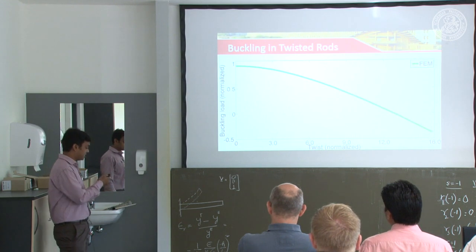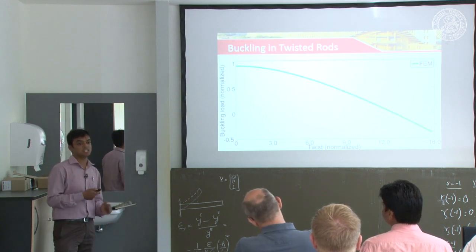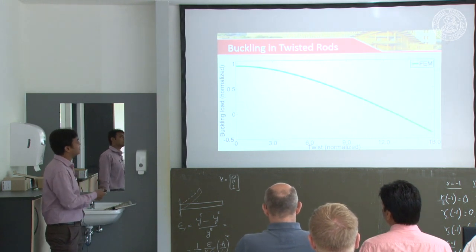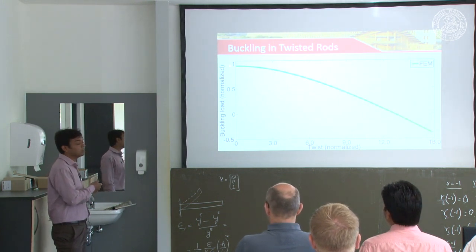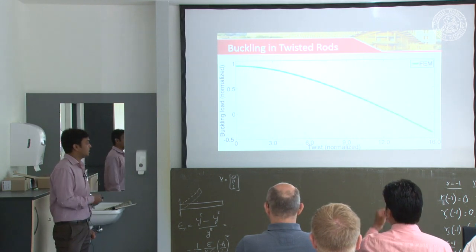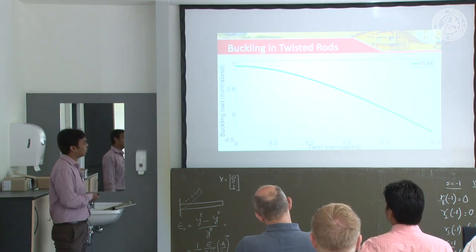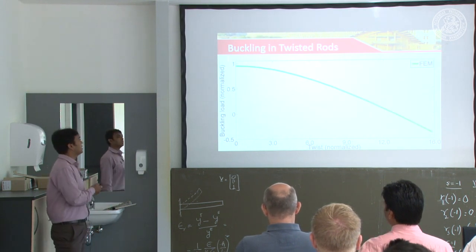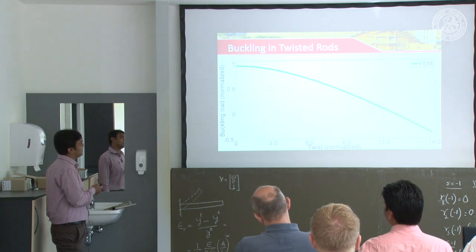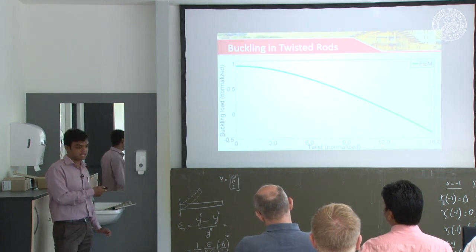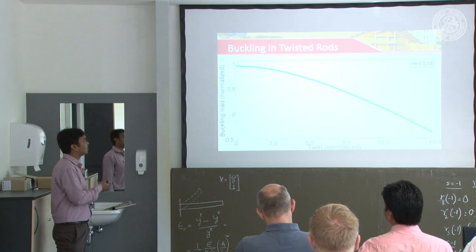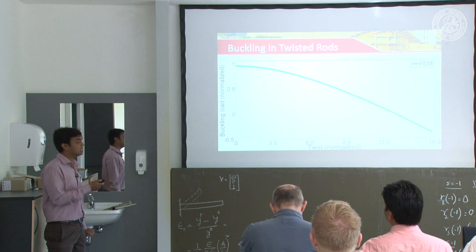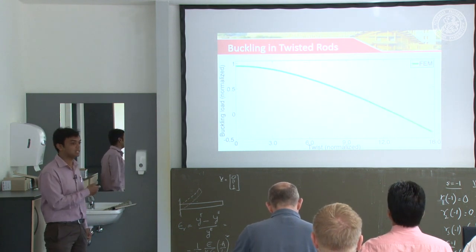So if I look towards the buckling load, which I again normalize with the Kirchhoff load, you see that in this plot, it does not start with 1. So your axis is twist, right? Yeah. I'm plotting my buckling load with respect to the twist, and at 0 twist, for a particular L by D, it does not behave like a Kirchhoff rod because the extensibility and shear stretch is being accounted for in the special Cosserat rod formulation.